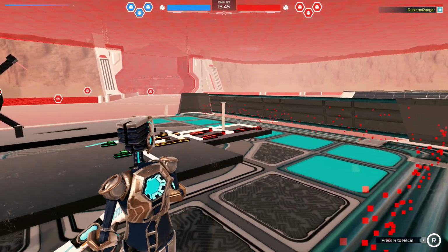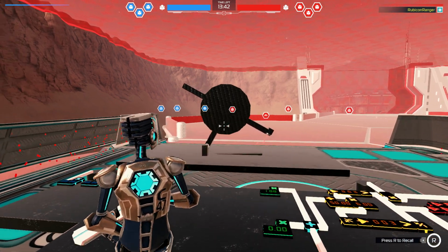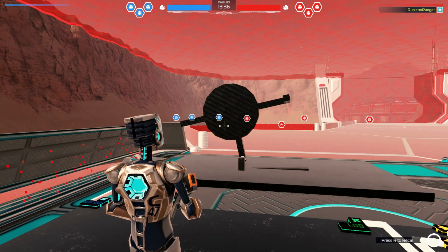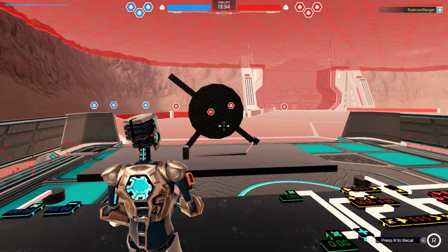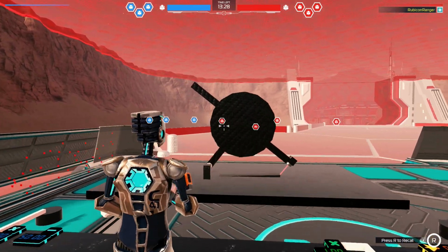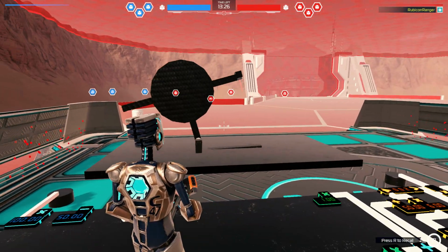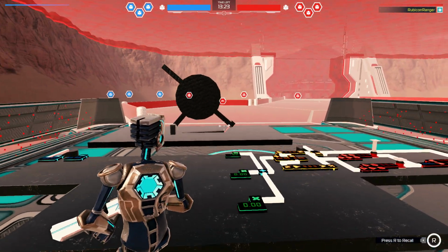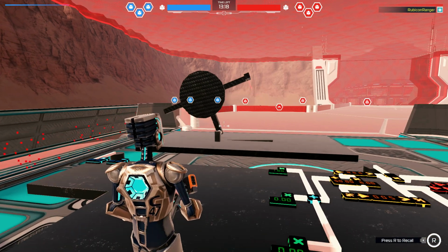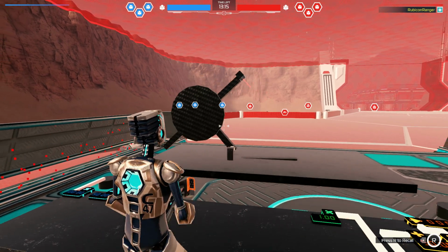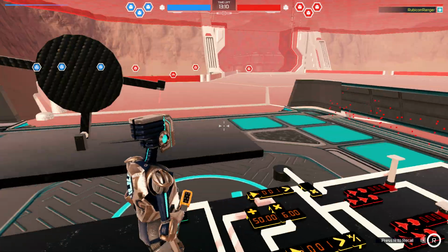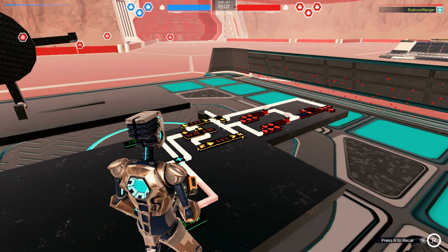Okay, so here the error goes up because it's over 50% duty cycle, and then it basically stops the wheel, runs it the opposite direction to come back up, and then gives control back to the proportional controller. So maybe this will turn into something, but it's just another thing that you can use. Oh, there we go. And it picks itself back up. So this is just another thing that you can use gyros for. And hopefully you can spend time on something and make it a lot smoother than this, right? Just based on how your blocks are set up. You can do it without having to have all this mess.